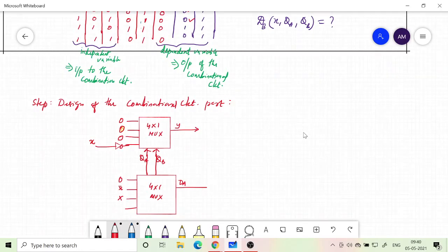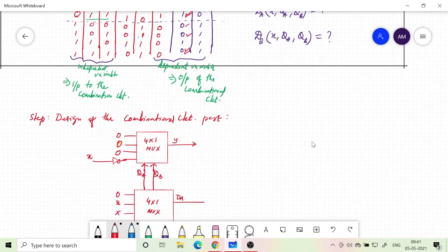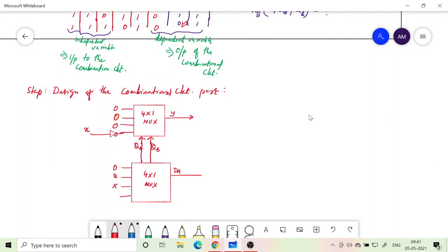And the last one, if you look at, it's going to be 1 0. 1 here, 1 here, and 0 here. So when X equals 0 it is 1, and X equals 1 it is 0. So this is like the second case. I will have X bar here. So you only need one NOT gate to generate all the X bar.